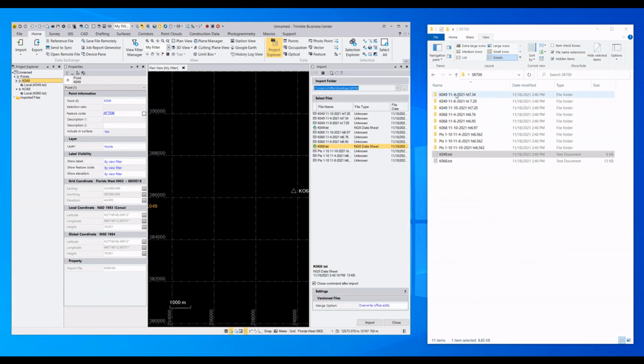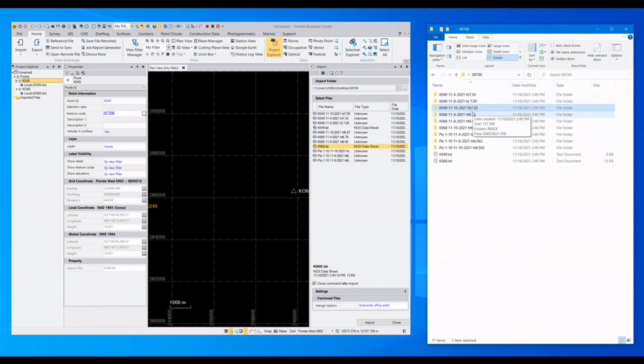So this file that I was sent, the folder has the point name in it and the date, I think, that it was collected, and then the rod height. And there's some issue here with some of these rods. Some were used with a conventional tripod, which I believe are these ones. And then the other ones, which you can see is 6.562 feet, which is 2 meters exactly, were, I believe, collected with a bipod or some sort of fixed height rod.